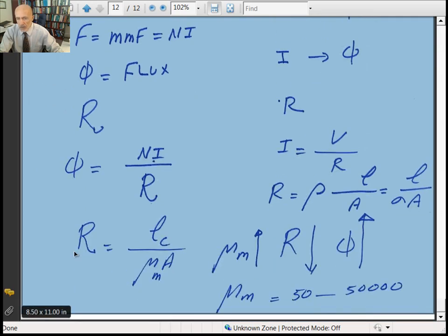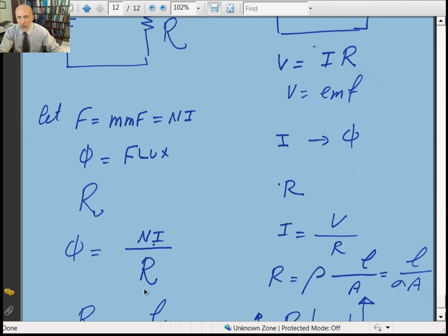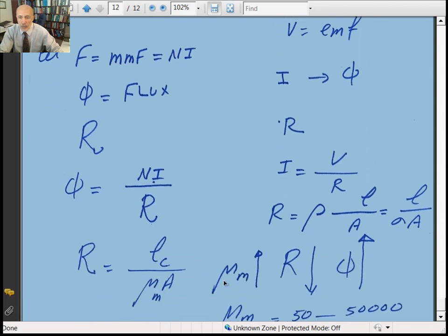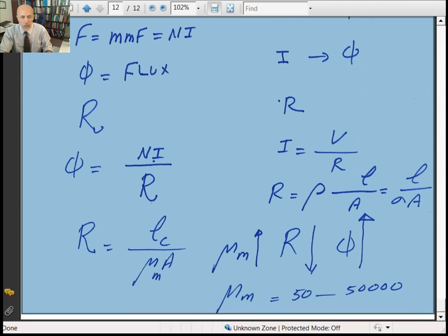And later on we're going to see when we talk about Faraday's law. Faraday's law did a very simple experiment. The faster you cut the line of magnetic field, the higher the voltage is going to be. So in the case of a power plant, the voltage in a generator is directly proportional to how much magnetic flux you have and how fast you're cutting those lines of magnetic flux. We're going to talk about that in more detail in later chapters. All right, we'll stop here and we'll look at some problems in Chapter 8 next time.